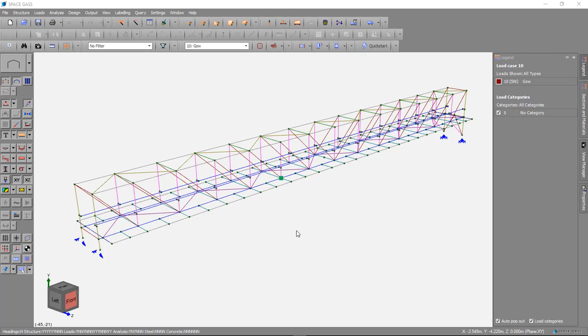So harmonic analysis is used to model loads that vibrate in a harmonic or sinusoidal motion, such as you could get with a crusher or a pump, a vibrating table, a motor, or any out of balance rotating or oscillating mass. It could also be used to model the effect of traffic on a bridge or a footfall analysis.